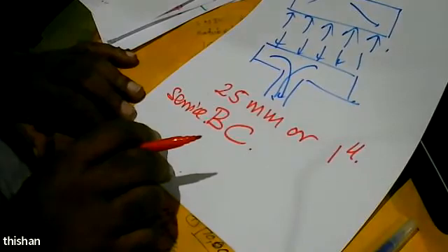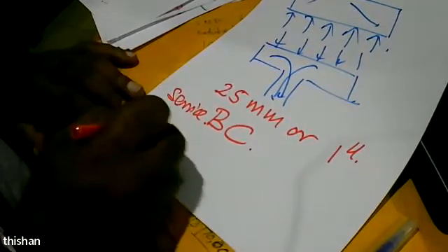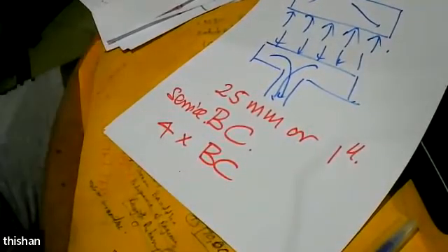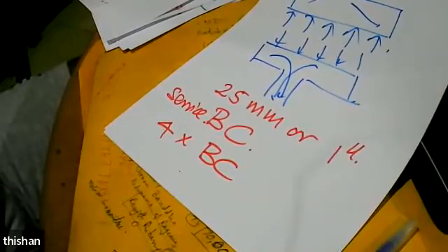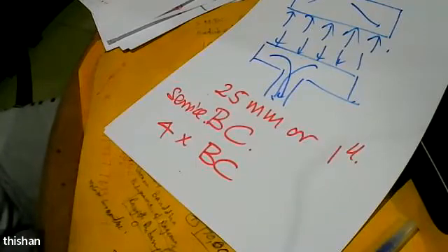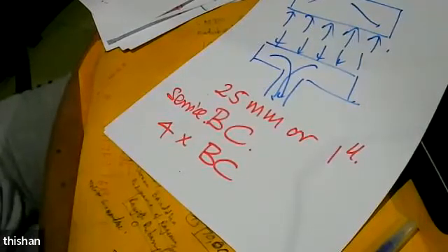Whereas when you consider the ultimate limit state, the soil strength can be 4 times or 5 times the bearing capacity. So the whole idea is you limit the deflection to 25 millimeters, and the load needed to create that deformation is called bearing capacity, which is a service condition. The actual strength of the soil can be 3 to 4 times more than that, but we don't use it in normal situations.